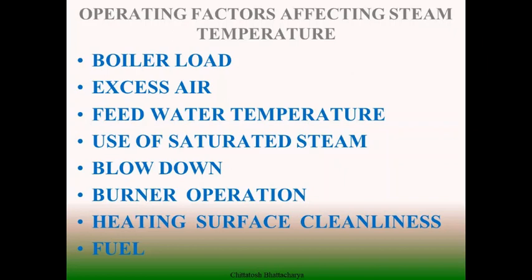Besides that, incoming feed water temperature plays a critical role. If feed water temperature is below the desired normal, naturally we have more heat absorption for increasing the feed water temperature to the rated level. So naturally the steam temperature varies for that.